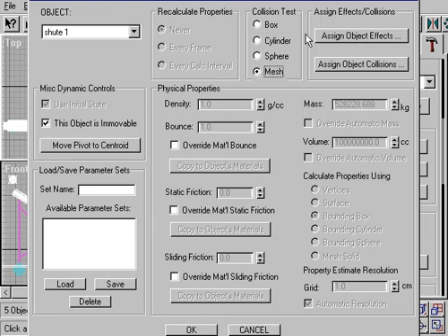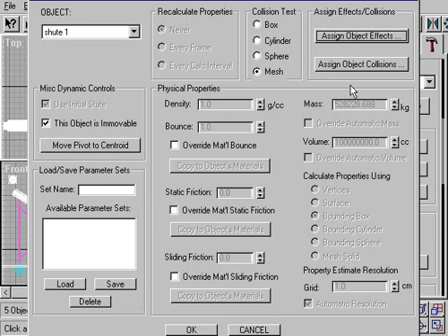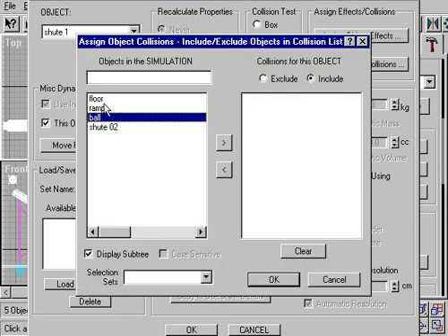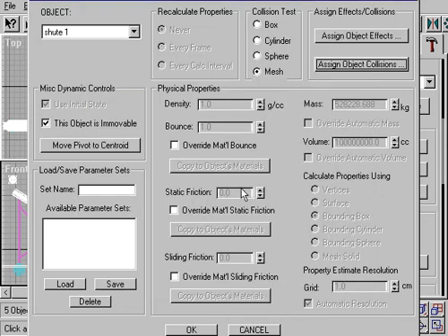When we select an object, the first thing we do is set up the miscellaneous dynamics controls. The two options are Use Initial State and the object is immovable. Basically, this is asking us whether the object is fixed in space or whether the object moves in space. The object within our scene is fixed, therefore we select the second option.